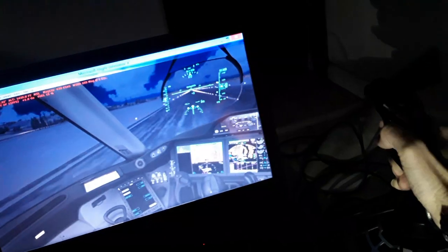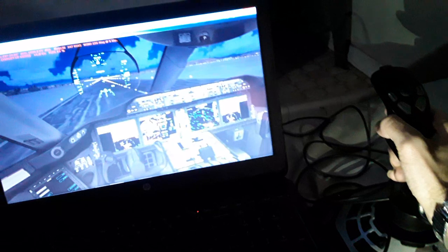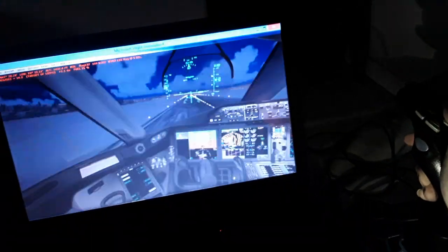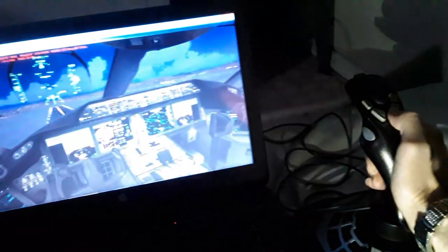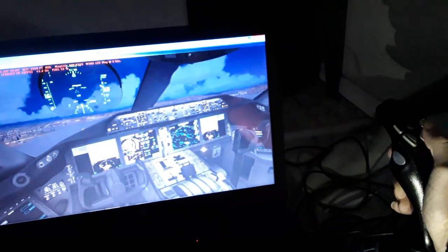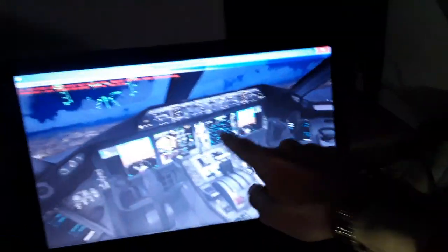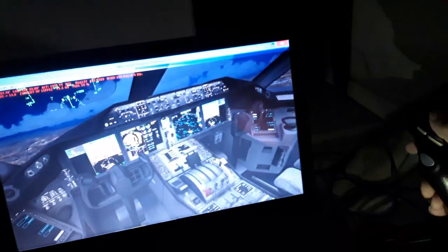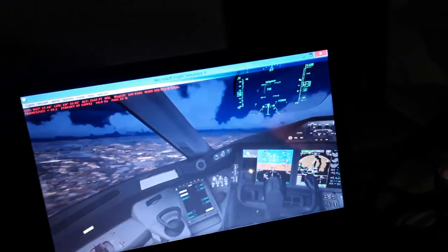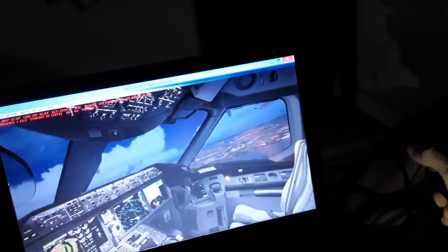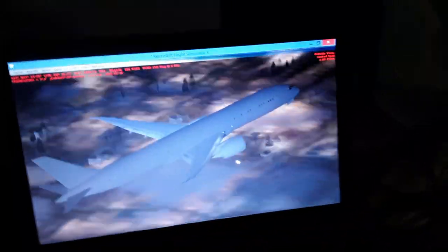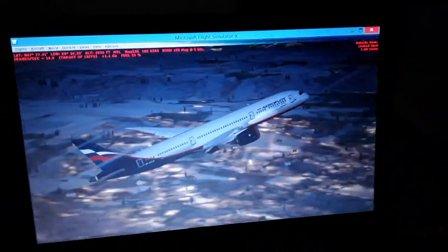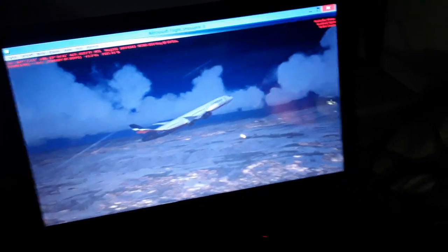V1, we rotate. So we pitch up like 9 degrees for the climb, for the takeoff rotation. We have maximum takeoff thrust, picks up a little bit. So we have the positive rate of climb, landing gear up, retracted. So keep climbing.